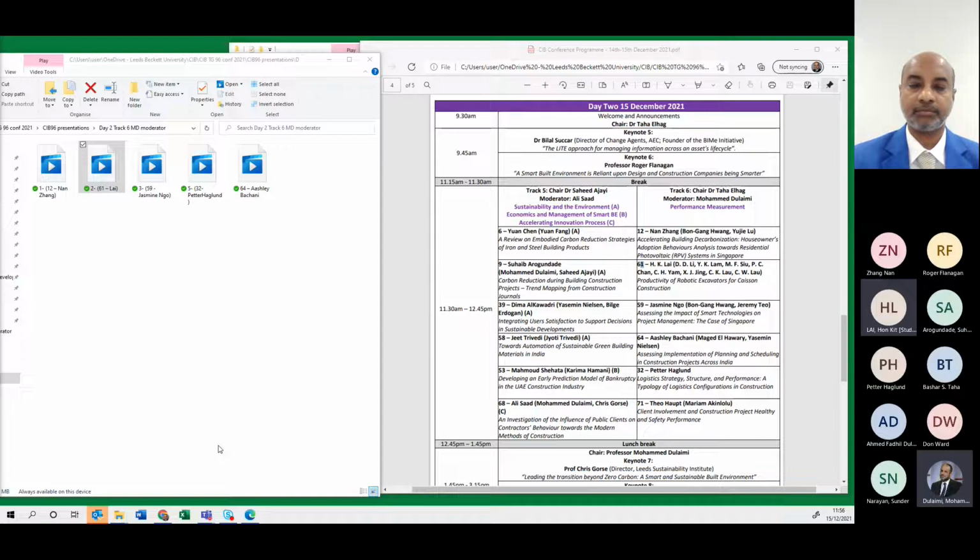It is quite space-occupying compared to a tiny or small construction site. But as I said before, the caisson method has the advantage of easier mobilization, because this method doesn't need very heavy-duty machines or piling equipment to construct a pile of the same diameter as bore pile methods.